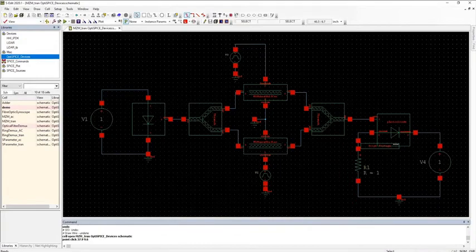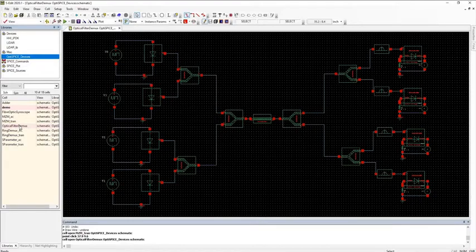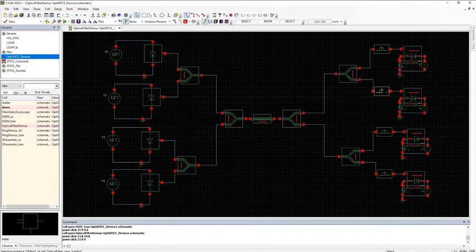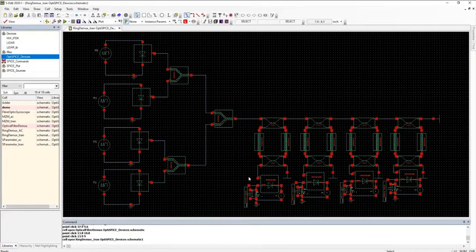You can also do more sophisticated simulations. For example, we have a filter demux simulation. So here we have a multi-channel simulation where each laser is set to a different frequency, and then all these signals are converging into one single waveguide, and then on the other side, they're filtered based on the channel. Here we're using an ideal optical filter, where you can set the center frequency, either bandpass or bandstop, and the bandwidth, and the frequencies will be filtered based on that. You can also design a demux with ring resonators.